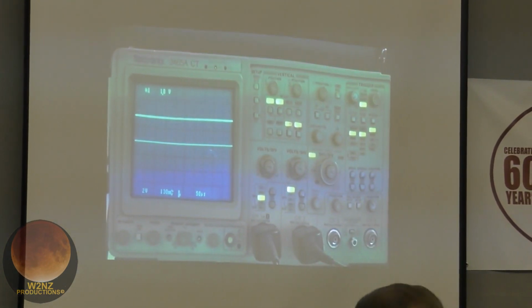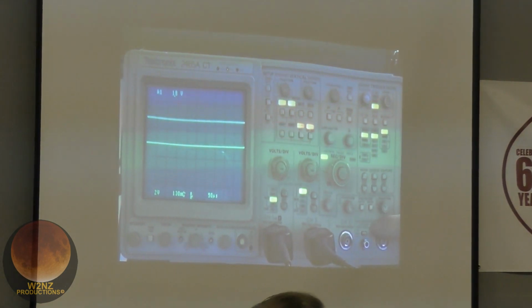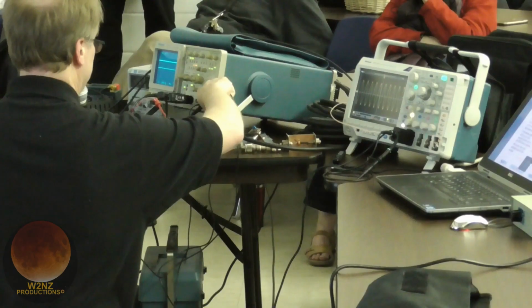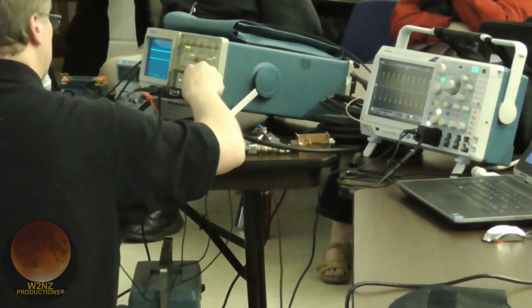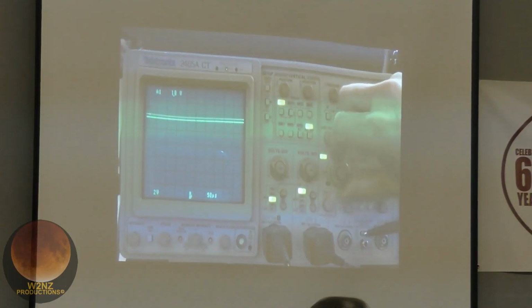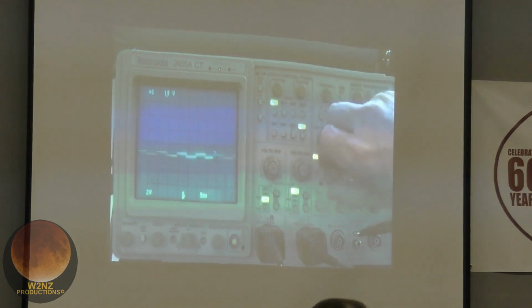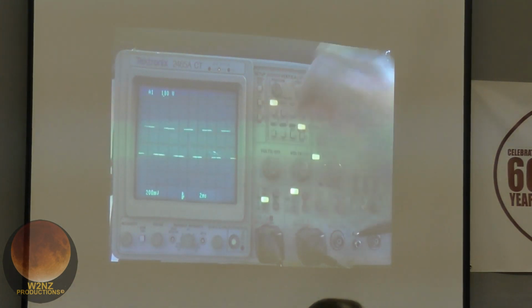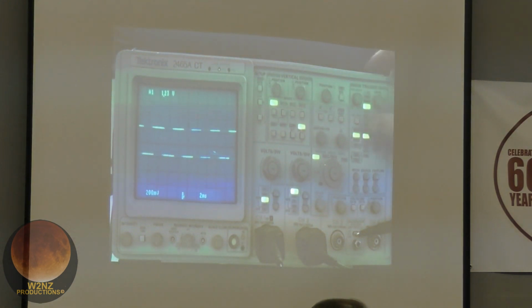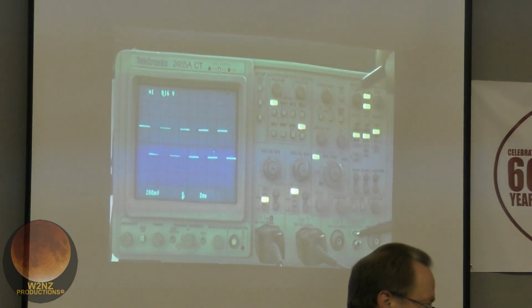Now on the front of the scope, you'll see oftentimes something that says calibrator or probe compensation. And that's basically a little spot where we can hook a probe up to. Let me turn off this channel, turn off my chop, and let's adjust this signal down. Let's go down to about a millisecond per division or so. Bring that signal up in amplitude, and let's go trigger on that. Let's see, here we go. So there's my square wave signal there. Now this probe is properly compensated. The square wave is perfect.